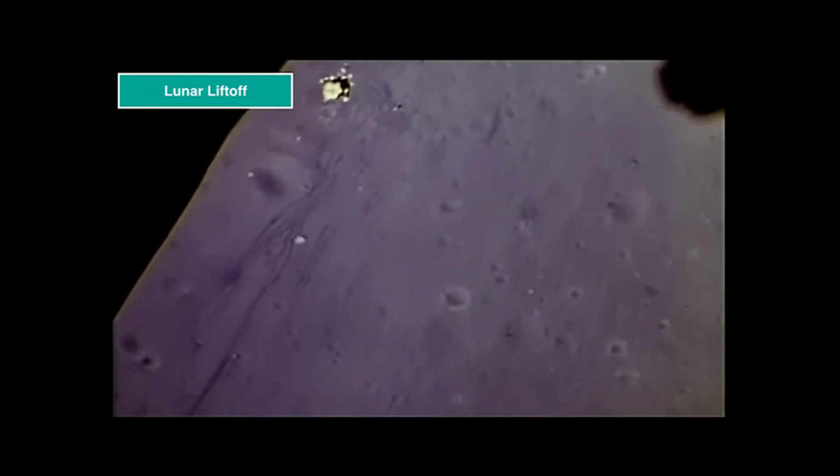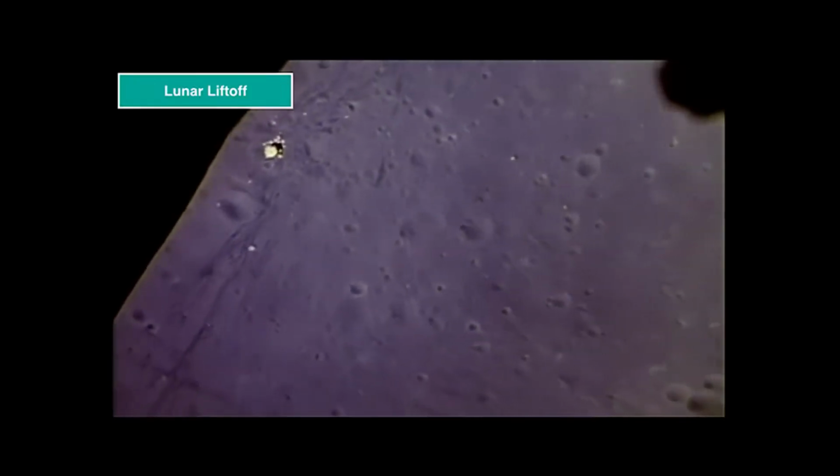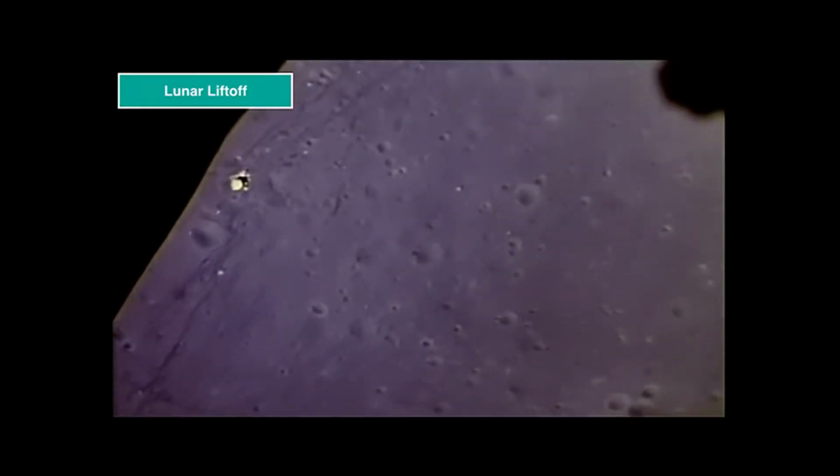The trip into orbit takes only 7.5 minutes, but depending on which method for reaching the target orbit was used, it takes us either 1.5 or 3.5 hours to come up behind the command and service module. During that time, program 20 is running all the time, measuring the state vector of the other vehicle, the command and service module, via various peripherals like rendezvous radar, VHF antenna, and the optics system for visual alignment. It calculates the necessary corridor and respective maneuvers required to get the lunar module into an interception course. Multiple other programs run in parallel to perform the necessary mid-course burn maneuvers.